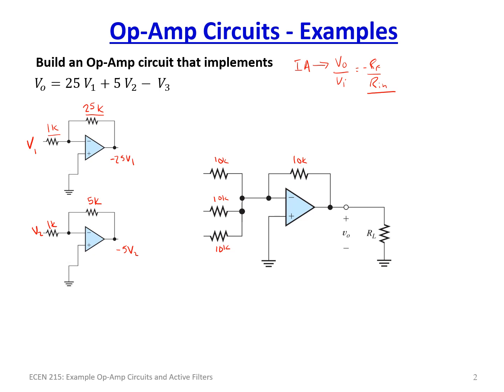So the overall gain of this amplifier here is minus RF over RN. And if these all happen to be the same, that's the same gain for each stage. Now you can have a separate gain that's RF over this particular resistor, so you can have one gain here, another gain, and you could have done this amplification of 25, for instance, here in this stage as well. And the output of these right here could have simply just been a gain of 1. So again, there's multiple answers to this.